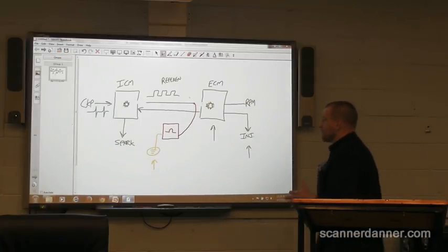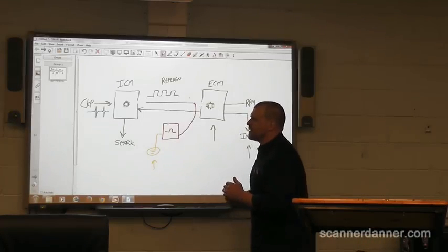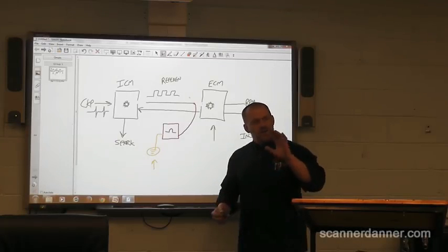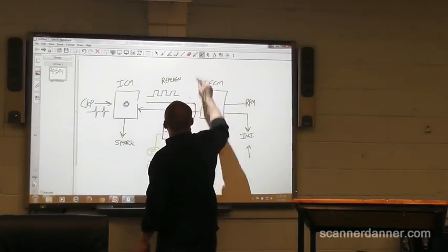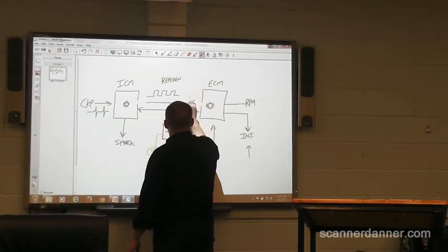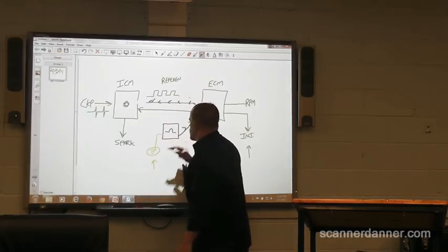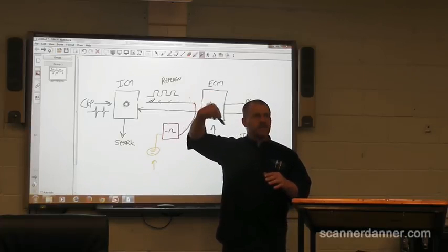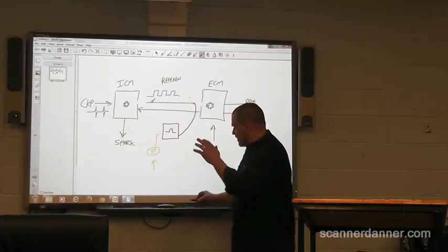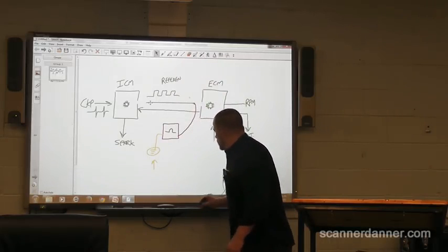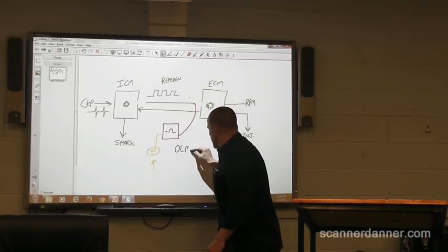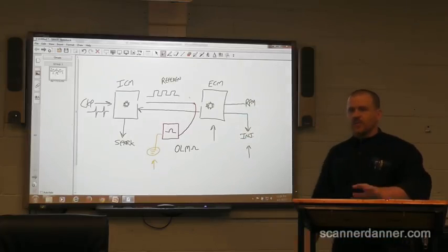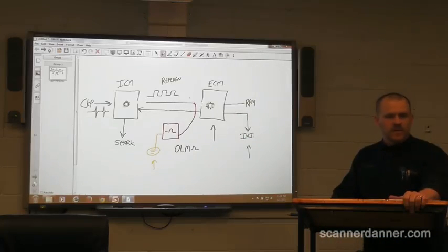For a short to ground test, we want to be on our highest one, because on a good wire, here's what the meter should do. This meter should send out a trace and it has nowhere to go. So the auto range feature of the meter will jack you up to the next highest scale, all the way up to M ohms. The only true infinity on this meter is OL, M ohms, which is what we should read for a no short to ground test. We want to be on our highest scale in this case.